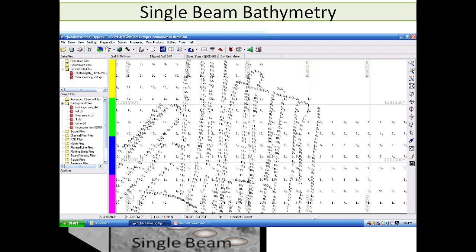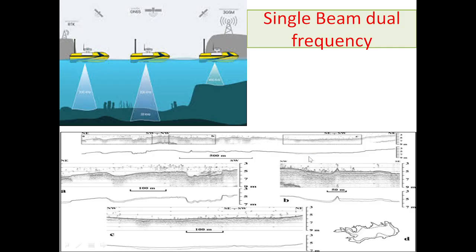This is like, as the boat moves, it is not in a logical way. So practically your boat cannot go on a straight line. It will move on its own way as per the site conditions, and you acquire the data and then you mathematically interpolate it in a gridded form. So lot of mathematics. What you measured as 5.7, what it becomes may be different, based on the many other algorithms. So it may take the average of 1, 2, 3, 4 and then put it. So all these things are the hidden truths. If you understand this, you will produce a quality output.